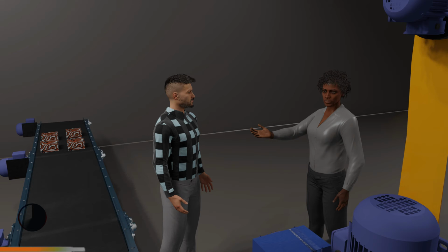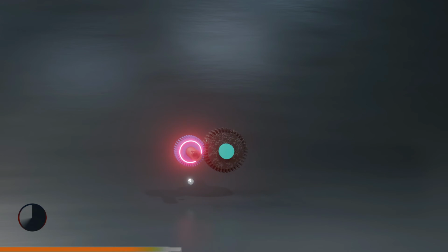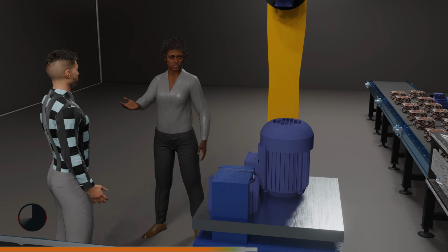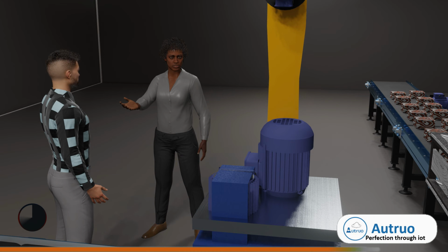That said, the reason why gears with reduced size produce more torque than gears of larger size is because the force acting on the shaft is a little bit closer to the teeth, and with the above ratio, in our case here, 3 or more revolutions are needed in order for the driven gear to make a complete revolution. And when we factor all these, then more torque will be produced.